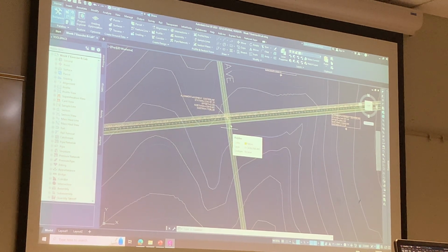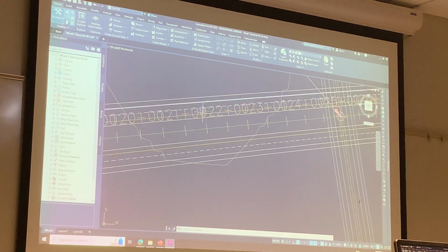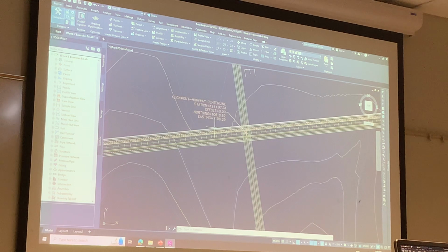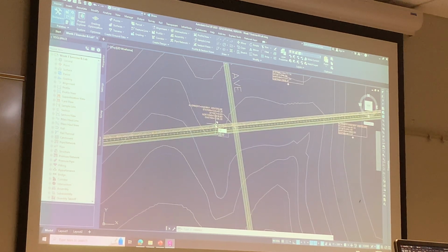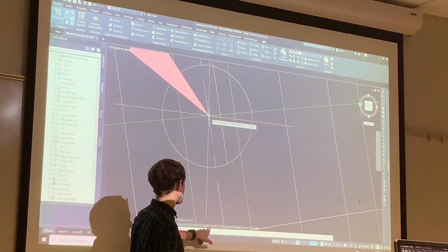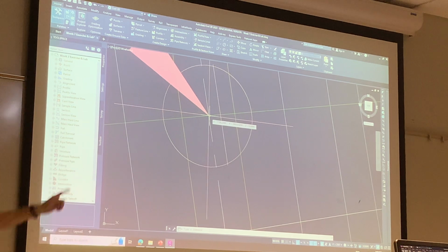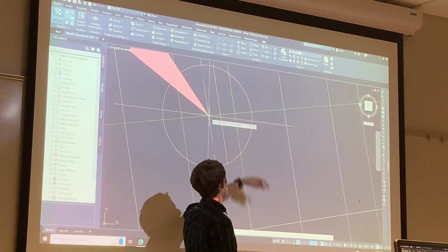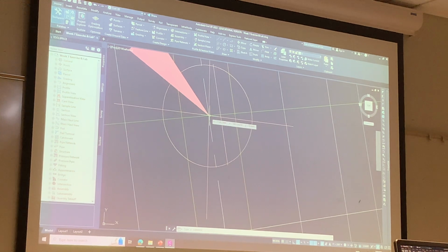If you want to double check that your points are all in the right spot before you start offsetting and creating alignments, you can type ID and confirm. It's going to ask us to specify a point. If I specify this point right here, it'll give you the coordinates at the bottom: 7106.29, 106.18. That also gives it to me right here as well.